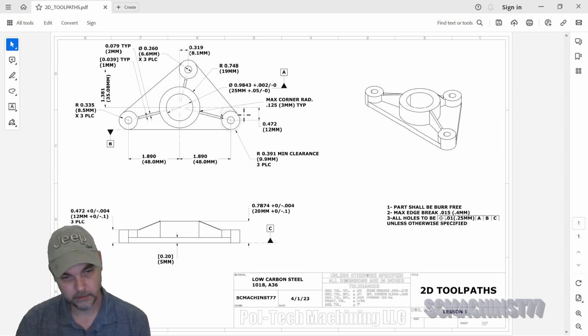In that consideration, when you're considering stuff like that, you want to look at, is this one piece or is it multiple pieces? We're going to treat this like it's a one-off part that we've only got to do one of. So when you get down to it, the quickest and dirtiest way to do it is the cheapest and how you make money off of it. So, all right, if we're going to do it that way, if we're going to mill vise jaws for it on the next op and hold it that way, what can we get away with machining?